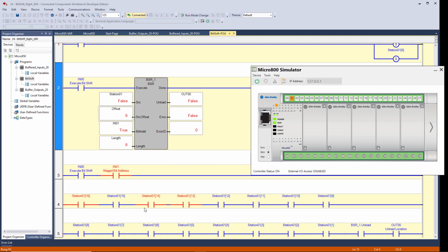So let's toggle these through. You think this in advance. Where do you think that this is going to unload from? 10, 9, 8, 7, where do you think? So I'm going to turn off input 1. I'm going to start toggling. Okay, the leading edge is moving from 13 to 12, 12 to 11, 11 to 10, 10 to 9, still there. Let's see when the unload comes on.